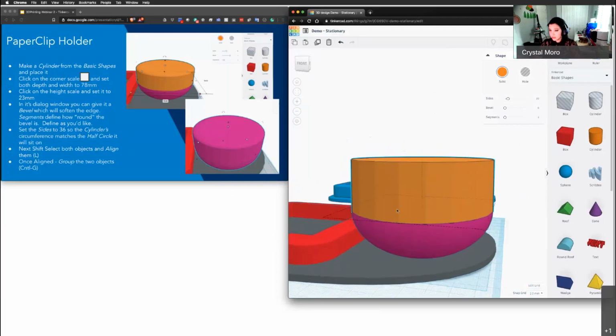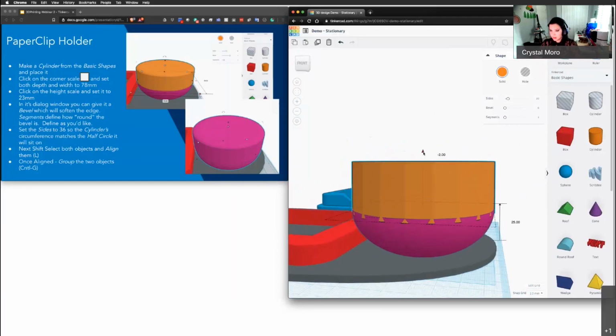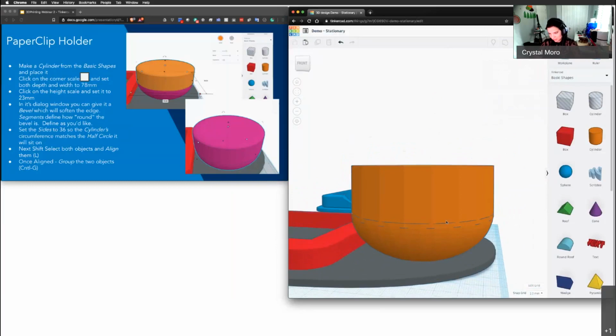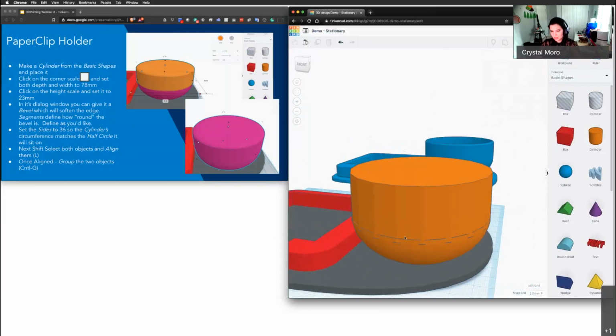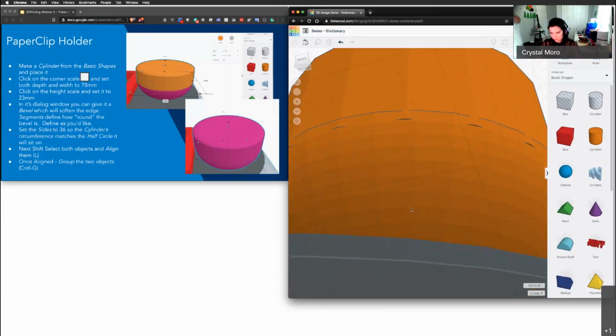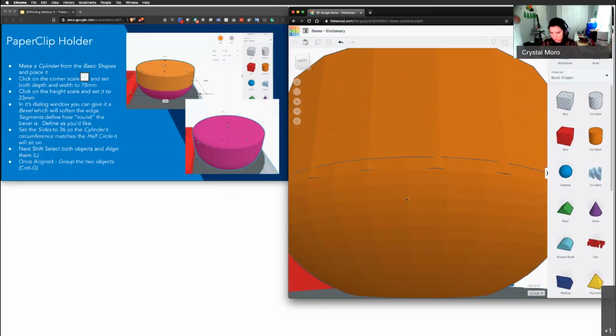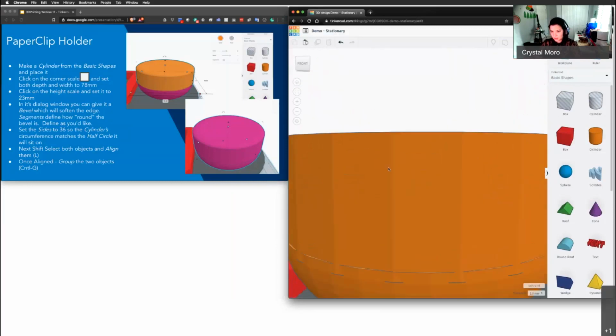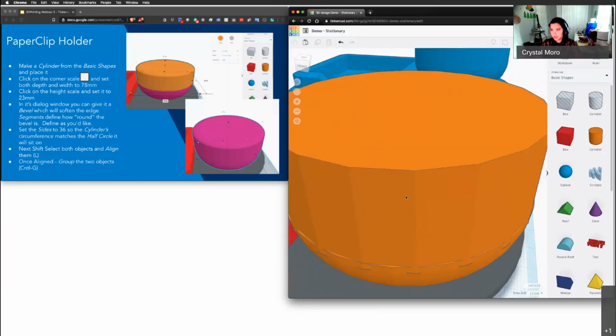And honestly, even if you combine things and the object's inside the other object, here I'll show you, it will combine it. But you can see you have that little bit of tessellation in here. And this is what I wanted to show you when it comes to 3D printing stuff, especially when you're combining stuff. The bottom half sphere has more facets on it than the top. So we have to adjust the amount of sides that the top has.